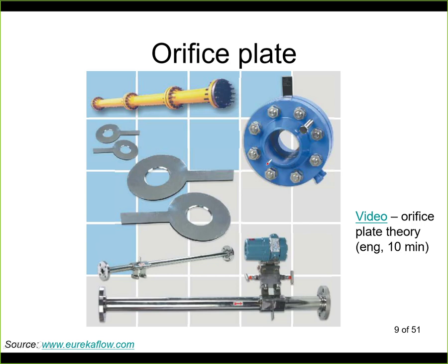And again, this is an example of the orifice plate. With a flange like this, you can disassemble those screws and you can replace the orifice plate. It's very sensitive to mechanical damage, so you need to have a precise shape here, precise angles here so that it measures correctly. And it's not suitable for applications with abrasive materials, for example.